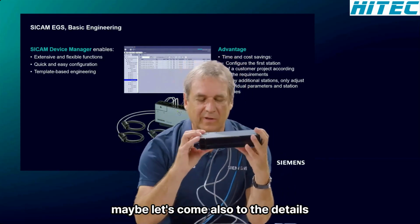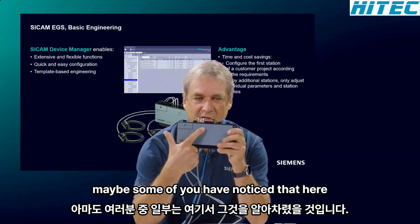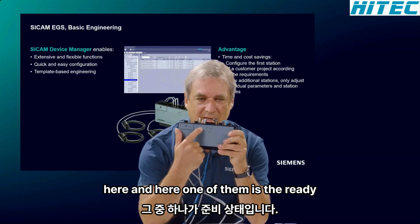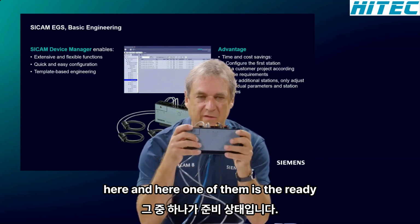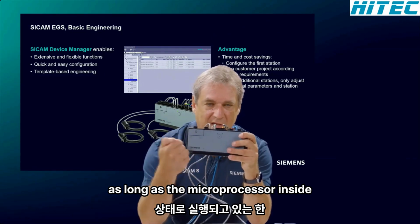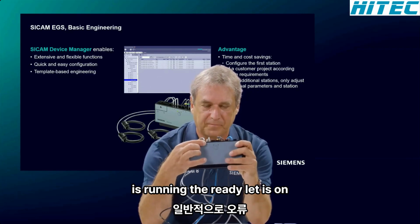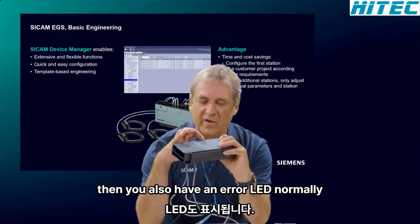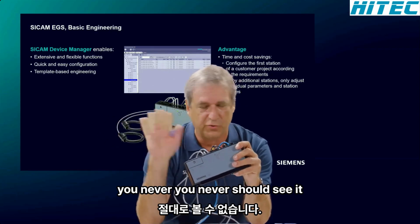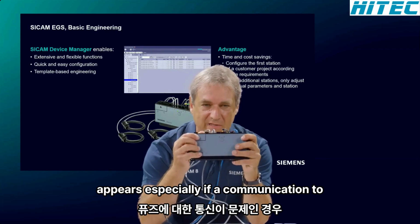Okay. Then, maybe let's come also to the details. Maybe some of you have noticed that here there are 2 LEDs, here and here. One of them is the ready LED. As long as the microprocessor inside is running, the ready LED is on. Then you also have an error LED. Normally, you never should see it. When could it be that the error LED appears?